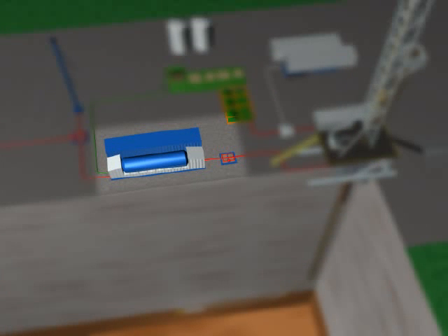Flow from the well is controlled via a choke manifold and then processed in a 4-phase separation system. This system separates the returns into its constituents: light fluid, crude oil, nitrogen and natural gas, and rock cuttings. The separated cuttings are collected for disposal.